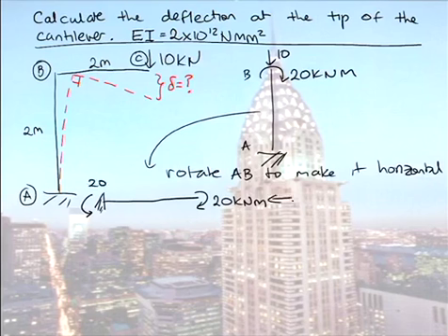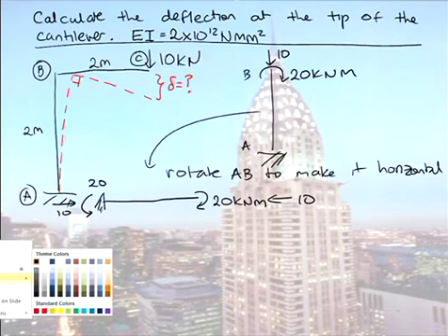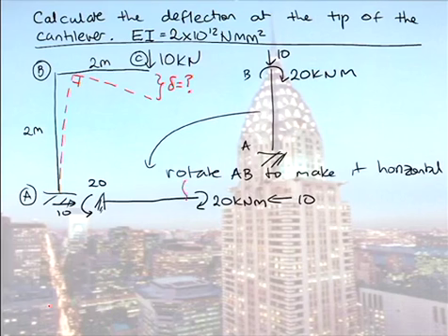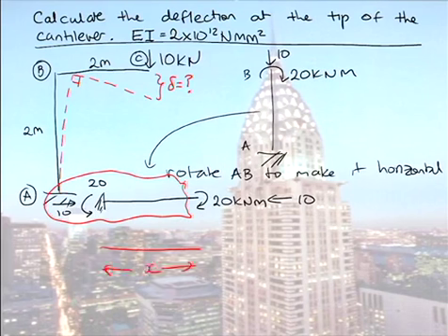There was a compression force of 10. There was a reaction force here of 10. So for my free body diagram, what do I do? I cut the beam as far left as possible. And I cut it a distance x. I draw my unknown moment. I have a moment here of 20 and an axial force here of 10.